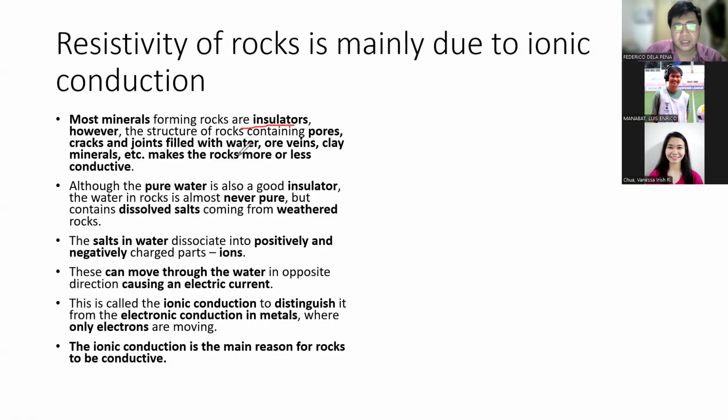However, rocks will definitely have pores. They will also have joints. And whenever these pores or joints or cracks are filled with water or conductive materials like ore veins or conductive soils like clays or other minerals, you get to actually lessen the resistivity of your materials.